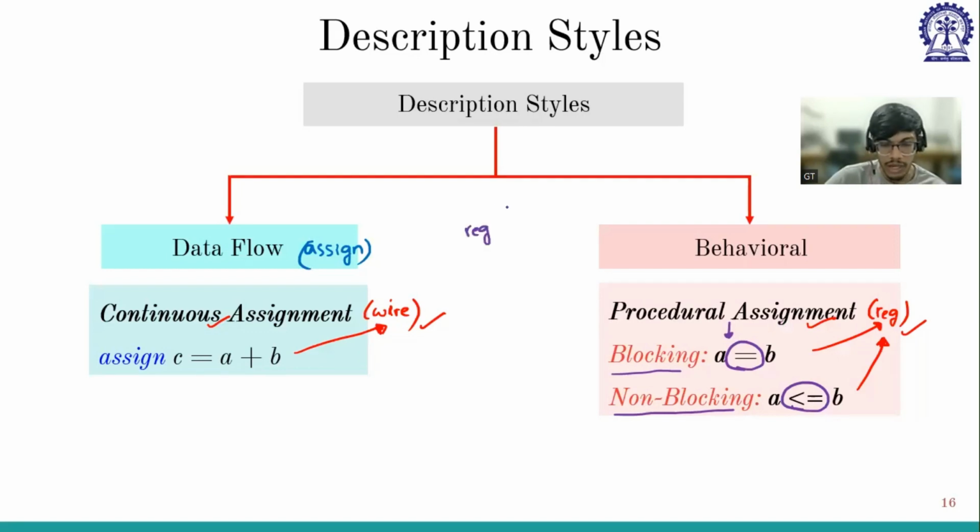If one or more variables are in the same family, you can put a comma and define them in the same line. Say reg [3:0] A; semicolon. Now B and C are single bit, so I have to write reg B, C; semicolon.